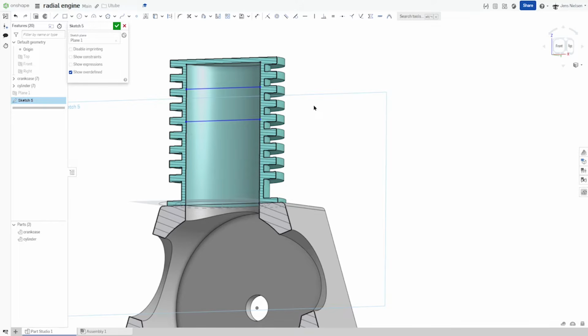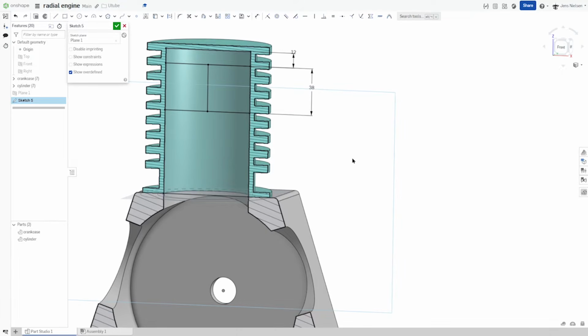So that's going to be our piston, right? I'll give that a value of 38 and a top distance for the combustion of 12, then a straight line through from midpoint to midpoint for the revolve of that one, and just a circle here with a value of 10 millimeters, and a distance here of 8.